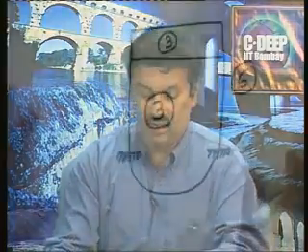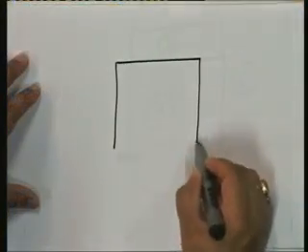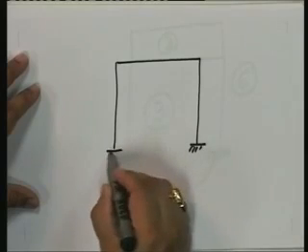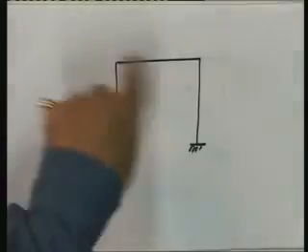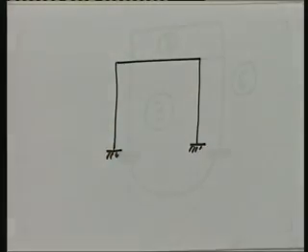Well, now, do I always have to take a fixed support? Well, no. Think about it. What do you mean by reducing the indeterminacy? How do you reduce the indeterminacy? Let's look at it. I have this single bay, single frame, which is fixed, right? So it's fixed. It's fixed. Now, we just discussed that this particular frame has 3 degrees of static indeterminacy.